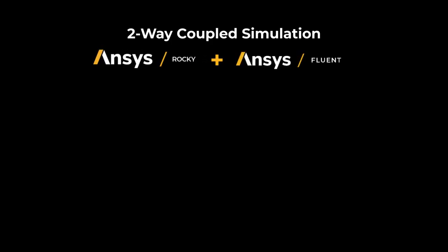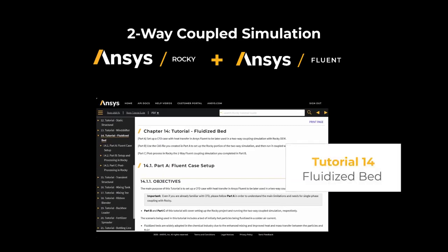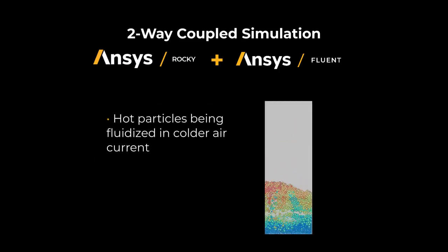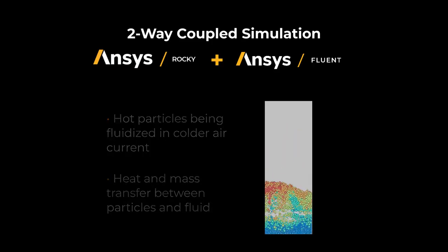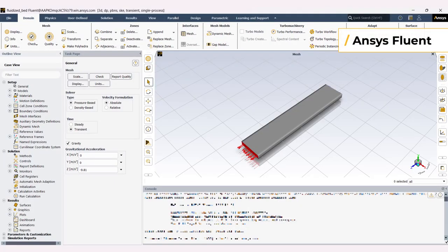In this lesson, we will demonstrate a CFD-DEM two-way coupling case using Ansys Rocky software and Ansys Fluent software. The case demonstrated is the fluidized bed, which is Rocky's tutorial 14. You can access the tutorial 14 from the links available in this lesson. The fluidized bed consists of a bed of hot particles being fluidized by a current of colder air. This is a common application in the chemical industry, due to enhanced mixing and improved heat and mass transfer between fluid and particles.